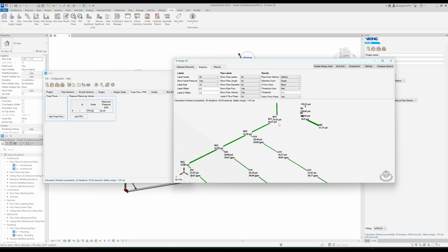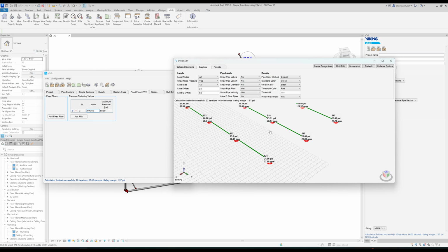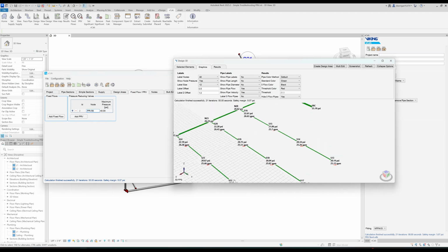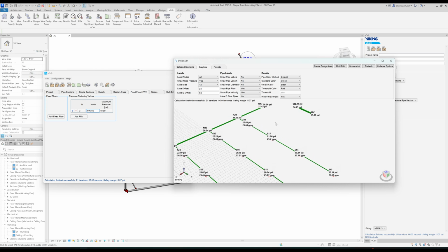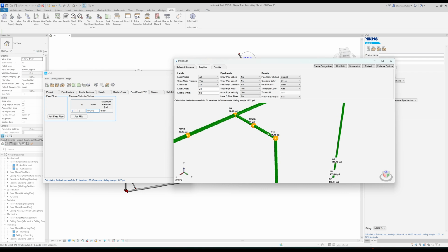We gain a little bit as we lose elevation, and if we look over here, we're still operating quite a bit above our minimum flow, so we could actually play with this maximum pressure a little more. So we try 40 psi. We can see that that helps some. We can continue trying to limit it to reduce the amount of flow that's coming down this pathway over here.